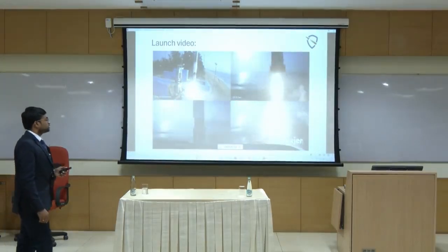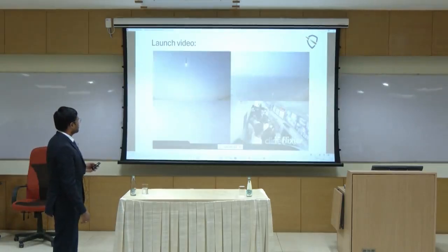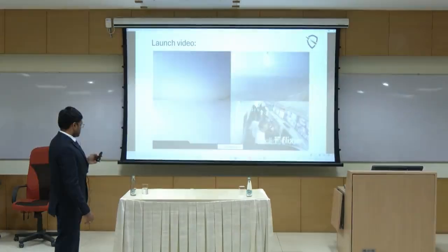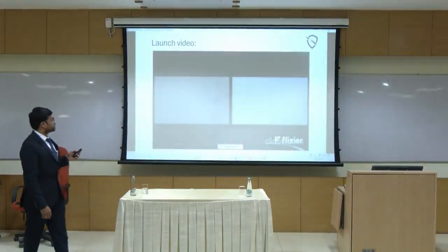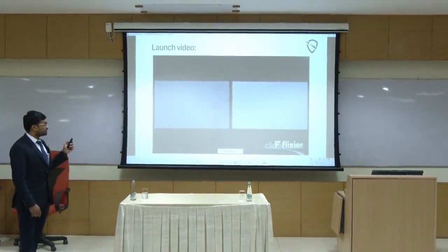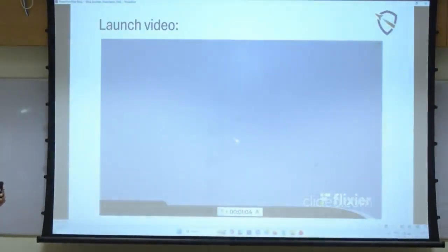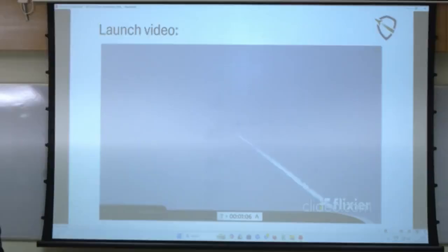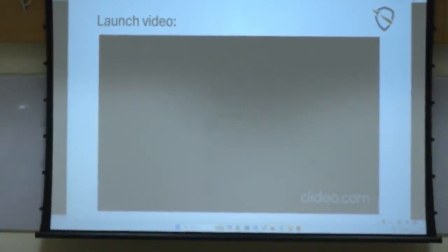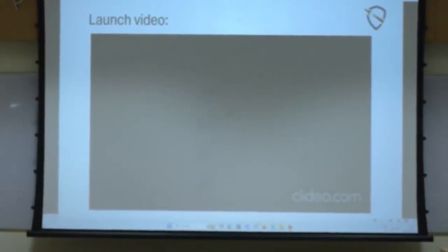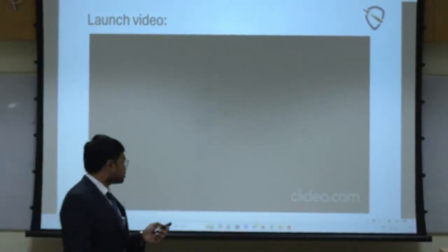So this we launched last year. The structure has to be optimized in terms of weight. This is very critical in launch vehicle companies because for 1 kg of satellite they charge 10 lakh rupees. So if we can reduce the complete structure mass by 1 kg, we can improve the payload capacity. But we need to make sure it withstands all kinds of loads.